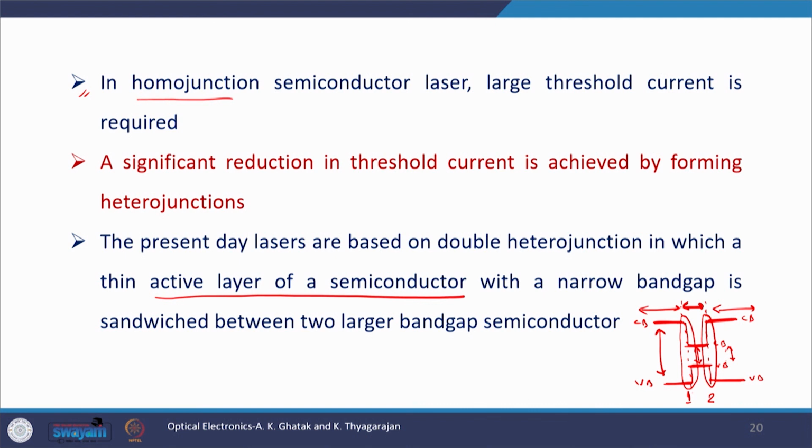This step is called a heterostructure or heterojunction, and there are two such steps, therefore, this structure is called a double heterojunction. Now, suppose we are pumping the system electrically, and an ammeter here is measuring current. It will put charge carriers here, and ultimately all charge carriers will come down to the lowest part of the conduction band, and therefore, the most probable transition would be in this thin region. This increases the efficiency of double heterojunctions.